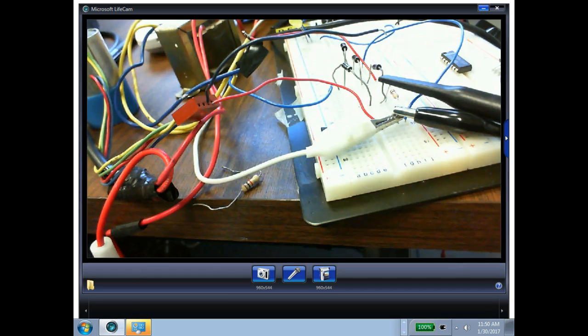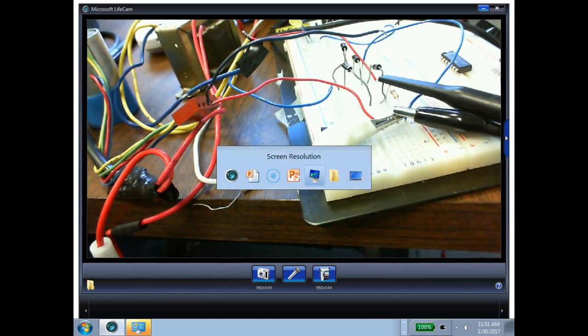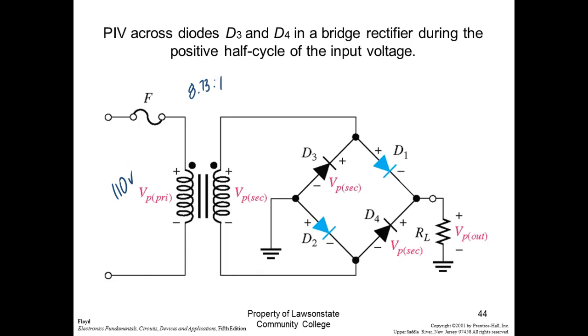Y'all understand that? Yes or no? Most industrial transformers, you need to read up on them. They can actually be reversed, so they don't label them primary, secondary. They label high side and low side. They don't use L, because L is used for inductors, so they use X on the low side. But on commercial transformers like this one, they're probably going to label primary and secondary.